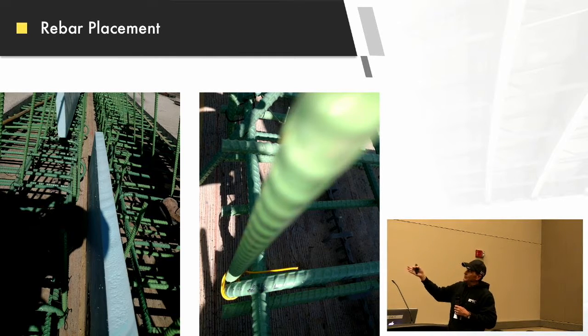And that's the other thing that's really important: as an inspector, you need to be out there with a wire or whatever as they're drilling, checking every one of the holes. Just because you've checked a couple of holes and they're good, you need to go back through and do a quick check on all the holes, and make sure they're clean before they place the epoxy, so the epoxy makes a good bond to the existing concrete and the rebar.